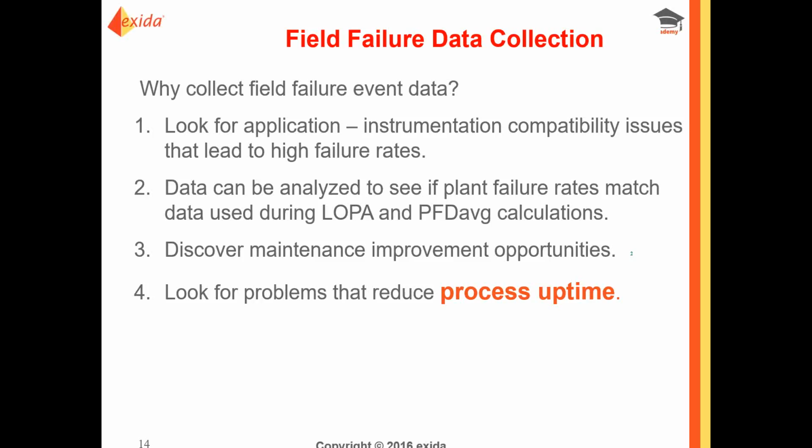And one great thing about manufacturers' warranty data is that often the manufacturer will trace the cause of the problem back to root cause. And many of those root causes have been identified as material incompatibility. That's important. We need to look for that, and when we find it, we need to change the instruments, or at least change the material in the instruments, very quickly to avoid future failures.